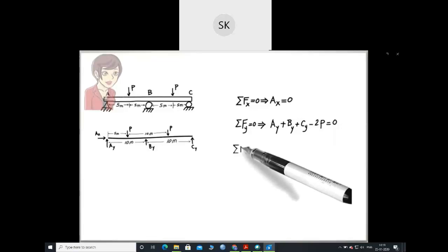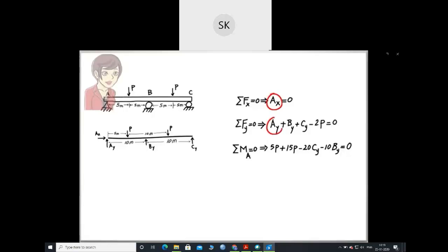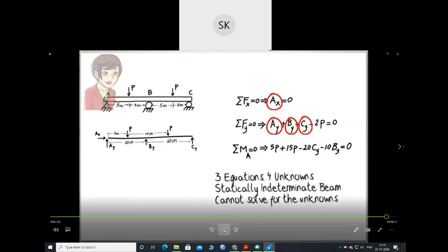5 times P plus 15 times P minus 20 times CY minus 10 times BY equals 0. Notice that we have four unknowns, but only three equations. Therefore, we cannot solve for the unknowns. The beam is not statically determinate. We will discuss techniques for...